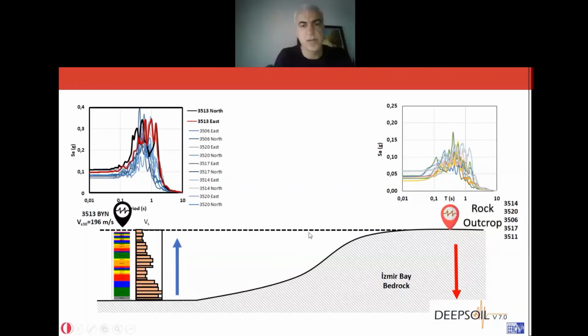Ahmet Hocam, as we wait, I have something in mind. It's not a question, but I just wanted to elaborate on Ozan Hoca's presentation. He has shown that the frequencies have changed. And we all know that the frequencies are dependent mostly on the mass and the stiffness. So after the earthquake, the change in the frequencies was in the range of 5 to 9%. And from visual inspection, there was no damage. So what might be the reason for this frequency reduction?